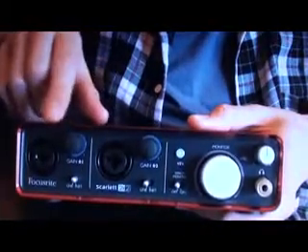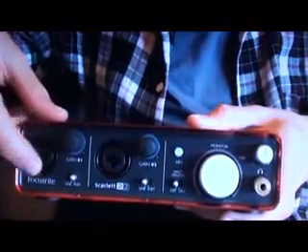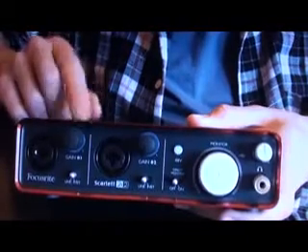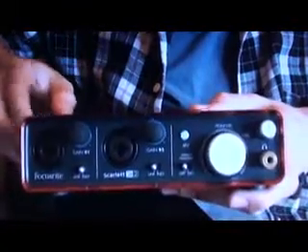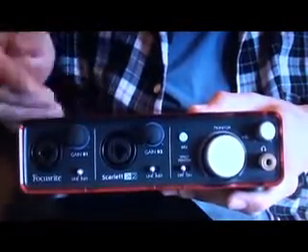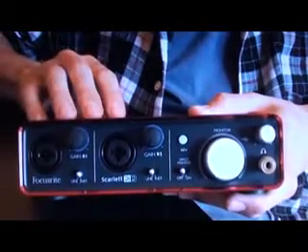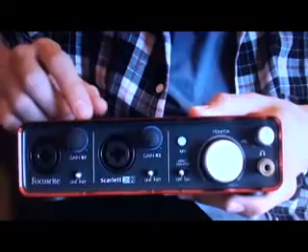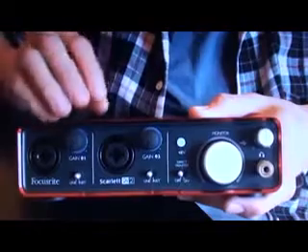Another important component of the audio interface is the preamp. The preamp is behind the input connector. It's important because when the signal passes through the preamp, it takes some color. This component adds some characteristics to the sound. But the most important thing is that the preamp brings up the input signal level to the standard line level. It's the principal function.